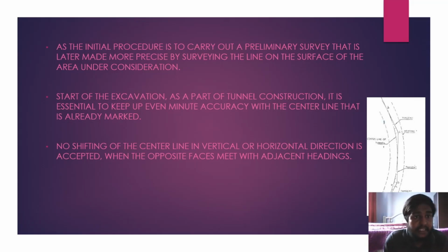The transferring of the center line is a method that must be done with great care, precision and accuracy. The accuracy throughout the execution must be guarded as it can give rise to many related problems. Carelessness can cause the lines from the opposite faces not to meet. Even small deviation from the centering can cause overbreaking. This undesirable work brings large expenditure, and it is more troublesome when the work proceeds through hard rock strata.